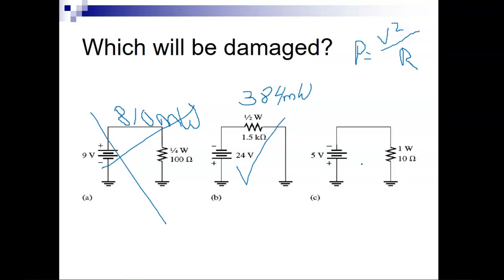And lastly, we have 5 volts and 10 ohms. Will this one be damaged? This one's 2.5 watts. What is our rating? Only 1 watt. So what's going to happen to this circuit? Because it's less than the wattage rating.